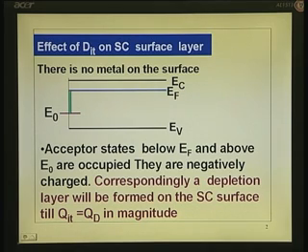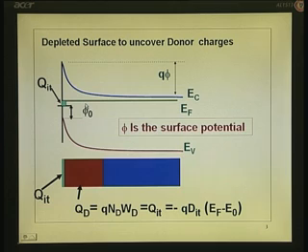Okay. The N type material, when it is depleted, has positive charge. It is depleted because those electrons have gone and occupied the surface states here. So, I have marked the total charge here as QIT. This particular diagram that I have drawn is actually the beginning. The moment this is charged with electrons, there will be a depletion layer, and the depletion layer charge will be equal to whatever charge is in the space charge layer. So, that correct diagram I have drawn next.